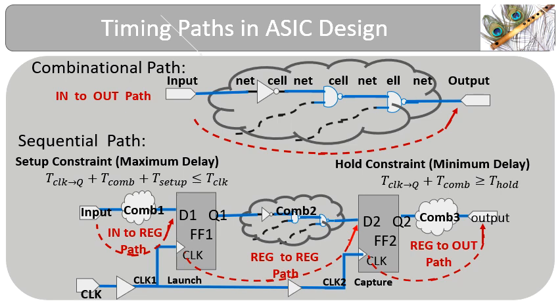The reg to output port path starts from the flip-flop, passes through the combinational logic and ends up at the output port. The combinational timing path starts from the input port, passes through combinational logic and ends up at the output port. The path elements of pins, ports, interconnects and gates are constrained by design and parasitic parameters that limit the operating frequency and may lead to a metastability oscillatory condition. Static timing analysis is employed to analyze all the path timings and thereby ensure correct operation.